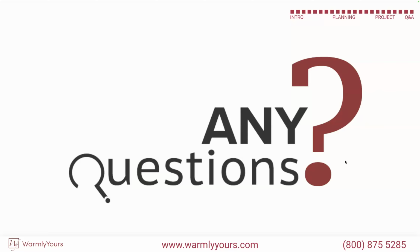So the tile, in this case, the perfect analogy is the tile is the product without a restrictor, and LVT, LVP, engineered wood, carpet, any of those type products are all throttled down. You can't go beyond a certain temperature limit. So if you had to heat an area like a 3-season room, which normally has a lot of heat loss, like skylights, like multiple windows, where that heat's going to escape, do you want to put an LVT product in that room, or do you want to put a tile product in that room? My choice would be the actual tile product in that room, because it's going to heat faster usually. It's going to transfer more heat into the space.